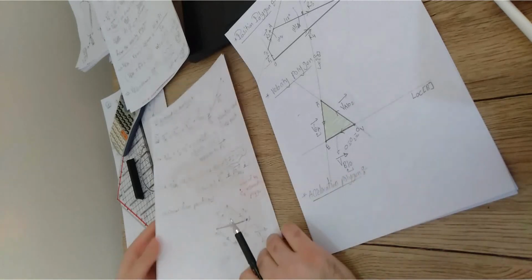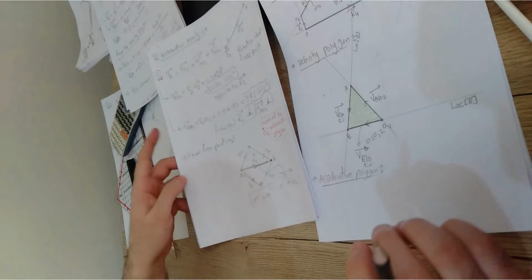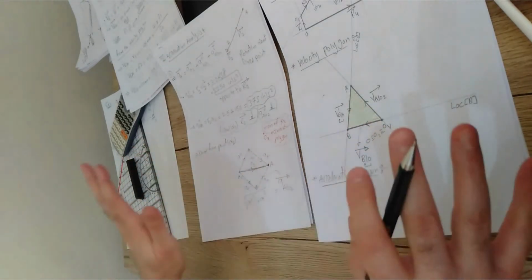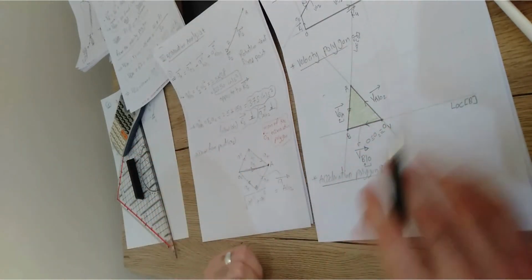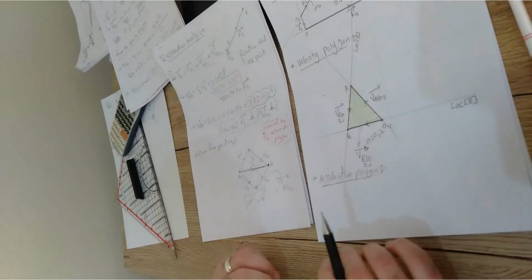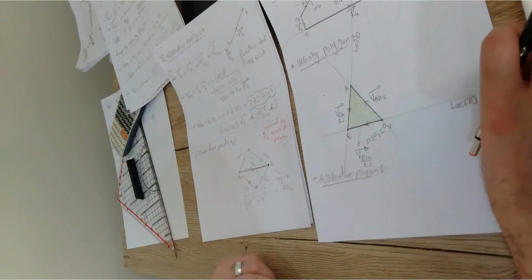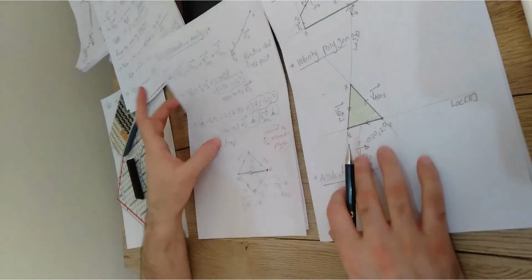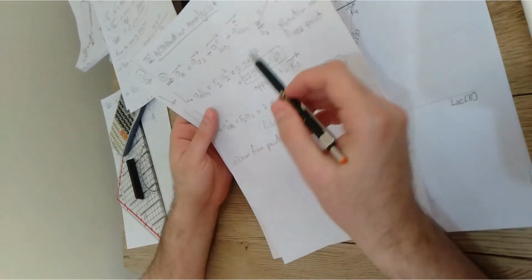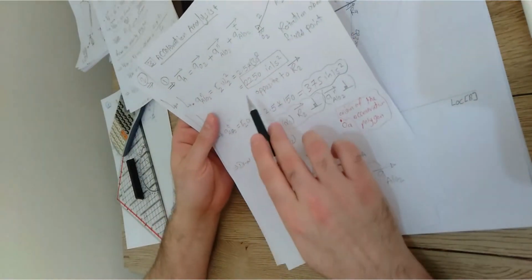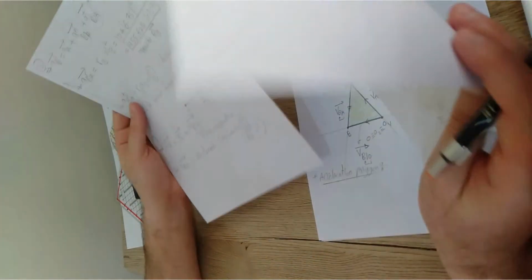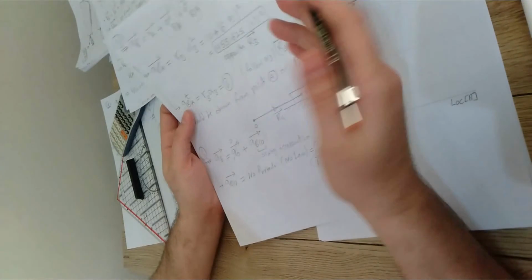So again, we have to specify a point. This point should be the OA point, which is the 0 point, the start point of the acceleration polygon that we're gonna consider here, right? But you have to have an idea about the scale of the dimension. We do have here some numbers: 2,250, 375, and 455. These are the three numbers.